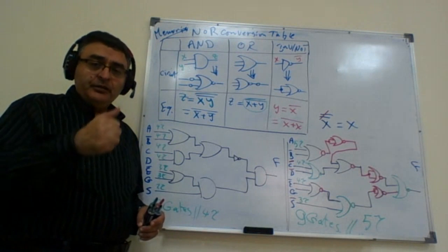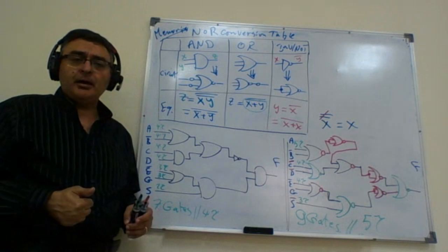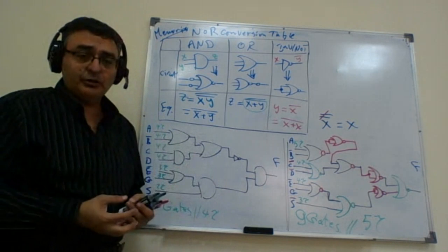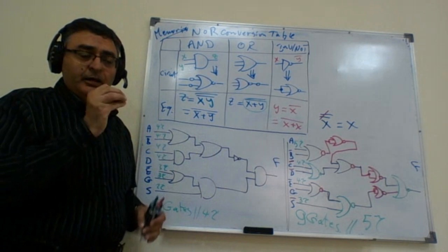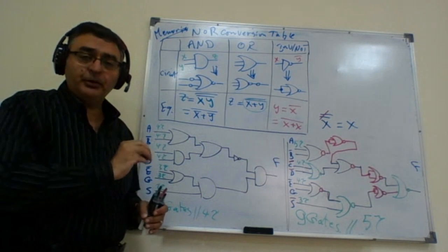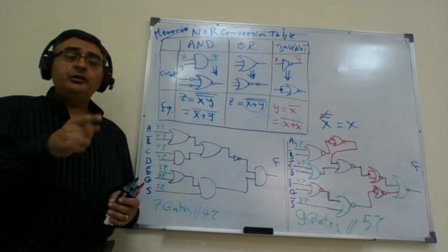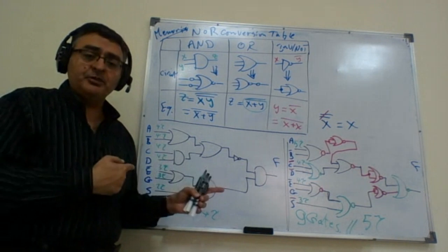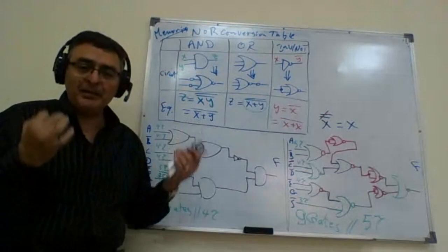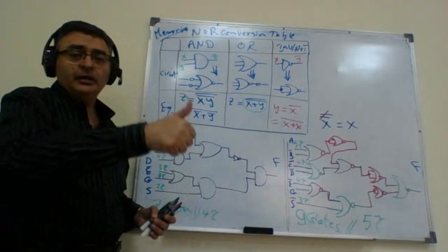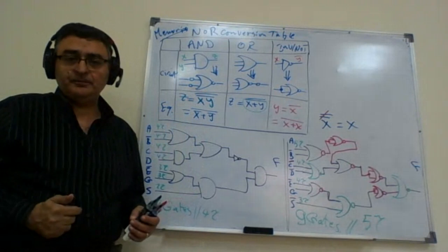This will achieve the minimum delay, since the K-map helps me to get the circuit in an SOP or in POS standard, which means minimum delay. And also, since we use the K-map simplification, I get the minimum format for the SOP and the POS.